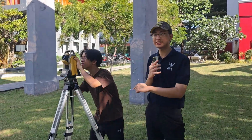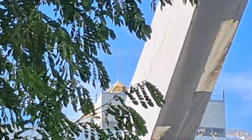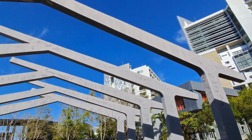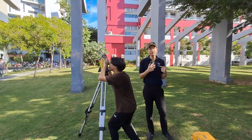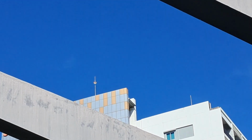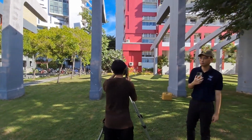The 2 angles we will measure by this total station setup are from this building at the top to the other building that we want to know the distance of. And the other angle that we will measure is from the same building to our prism.